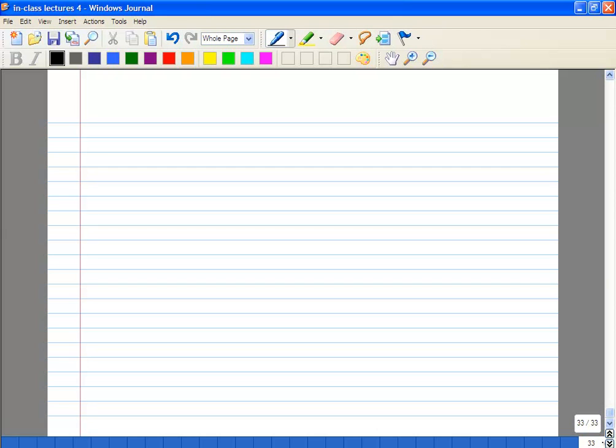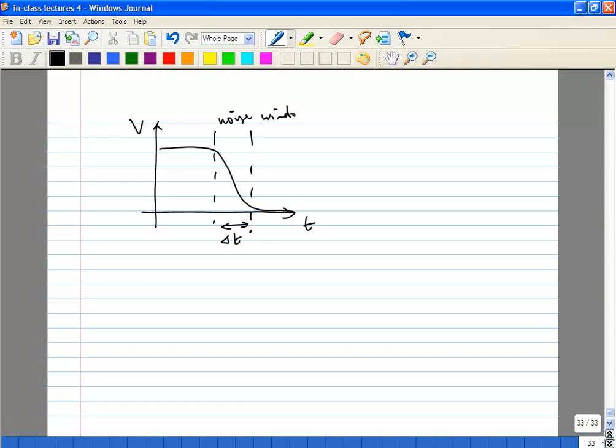Now the last thing you have to worry about is for the inverter, if you take one switching instant, obviously the inverter itself is going to contribute maximum noise in this window while it's switching. Obviously any noise which is injected by the devices or externally is going to change the switching instant. So that is what is going to affect your phase noise.